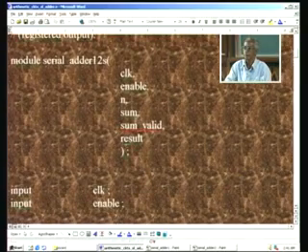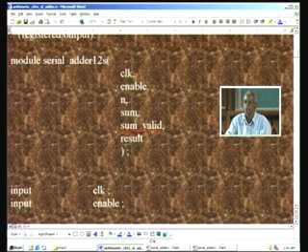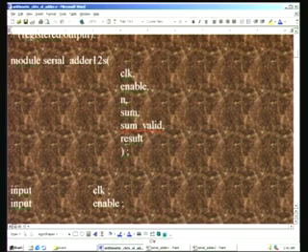This is the module declaration for the serial adder, and we give an apt name here because it is a serial adder. We give this name, and it is 12 bit and signed, that is why this name has been given, and you have to list all the IOs here. According to the block diagram we have already seen, clock, enable and n are the 3 inputs, and sum, valid and result are the 3 outputs. Sum and result are primarily the same output. The difference is that the sum will be valid only for 1 clock pulse duration, whereas this result will be valid for 9 clock pulses, and that is the difference between the 2.